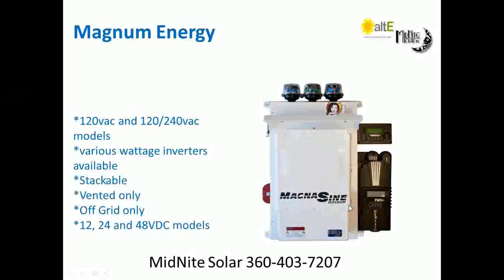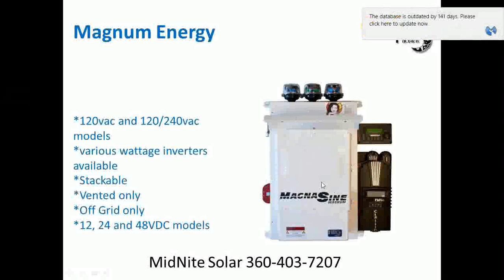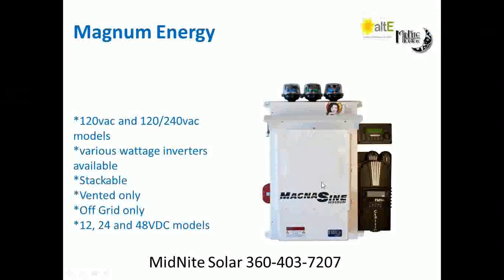Again, they are stackable. The PAE series can stack up to 4. The regular series can stack up to 2. They're all vented, so if you're in an area like Hawaii and that's a concern to you, again, the Outback is sealed. The Sunny Island is fairly well sealed, not necessarily sealed, but well protected. The Radian is not sealed, but it does have conformal coating on most of the boards, so those are things to take into consideration.